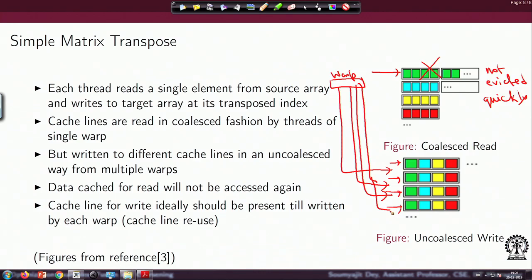So, there will be multiple cache transactions happening. At any point of time, there are a lot of write instructions in flight, and the average latency of the cache write is very high, and that effectively increases the amount of time for which I am unable to evict the data from a cache line. I hope this is clear. As long as I am not able to read as well as write back the data column-wise, I cannot evict data from the cache, right. Now, since the writes are getting serialized in this case, I am unable to actually evict the data.